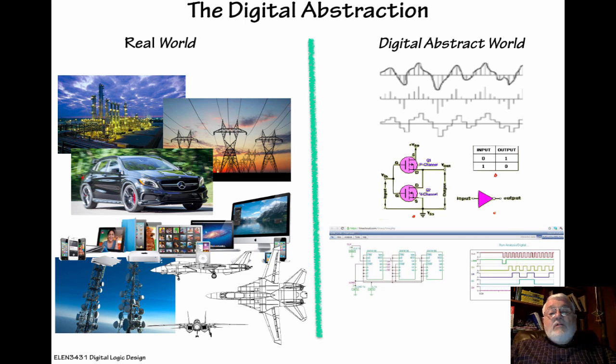And then the middle diagram, we're going to get to that very, very soon. Those are CMOS transistors, MOSFETs, and we're going to use MOSFETs in order to do logic. The little table in the upper right of that middle diagram is what's called a truth table. It's going to tell us what the digital values, the binary values of the output are based on the binary inputs. And then, A was the transistors, B is the truth table, and C is the schematic or the symbol, and that's an inverter. Remember we had the inverter with the TV picture, the black and white picture? So if the input is a 0, the output's a 1. If the input's a 1, the output's a 0.